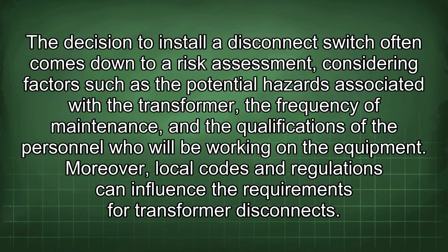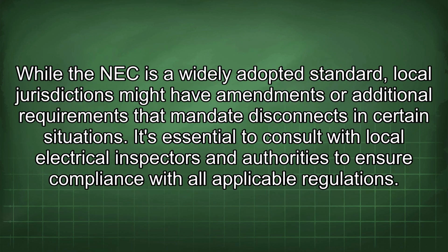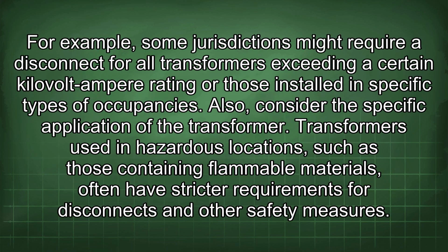Moreover, local codes and regulations can influence the requirements for transformer disconnect. While the NEC is a widely adopted standard, local jurisdictions might have amendments or additional requirements that mandate disconnects in certain situations. It's essential to consult with local electrical inspectors and authorities to ensure compliance with all applicable regulations. For example, some jurisdictions might require a disconnect for all transformers exceeding a certain kilovolt-ampere rating or those installed in specific types of occupancies.